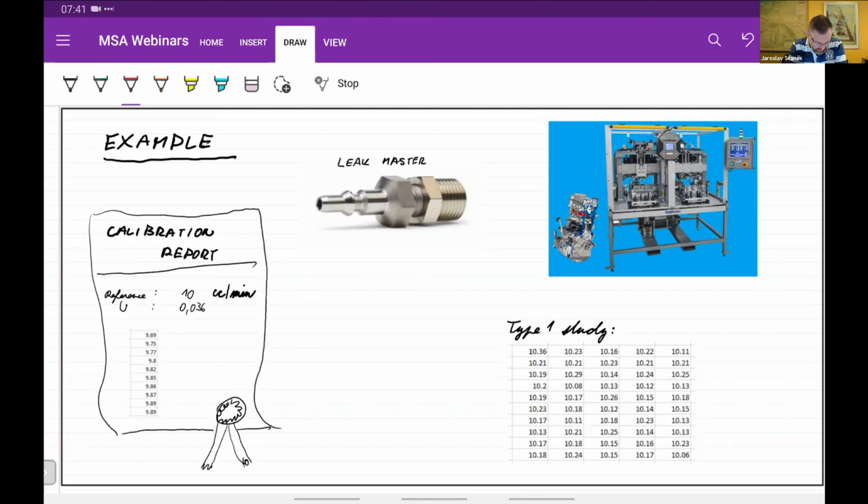And we'll no longer speak about the measurement itself, although it's a very interesting topic, but about the uncertainties, just the uncertainties. So if we have a measuring machine like this in a production line, it is pretty easy to make a type 2 study or to check repeatability, because we have the objects, we have the operators, we can measure the parts repeatedly and see what that component of the measuring process is.